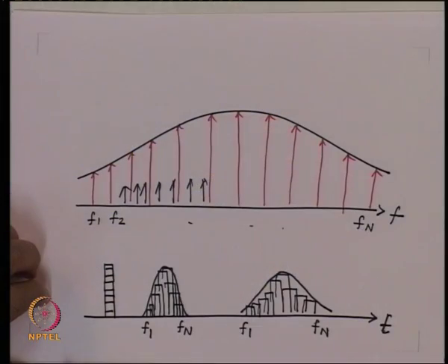So, the shape of the pulse and the spectral width required, both of them are decided by the carrier in the optical communication system, and this is conceptually different than what happens in the radio system. Once we understand this, then the next thing is straightforward, that if I transmit now more and more pulses, then this broadened function will start overlapping with each other, and because of that the signal will slowly start losing its identity.